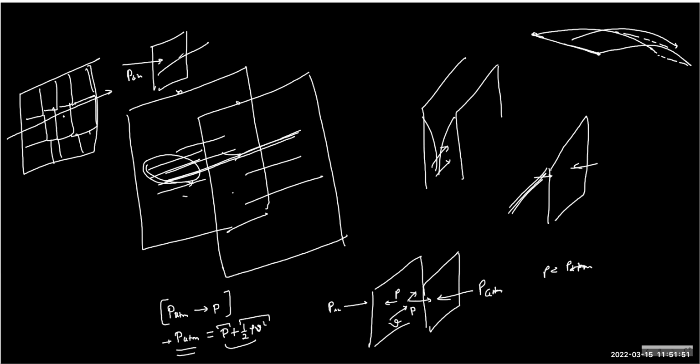So during a storm, what happens? The wind flows so fast that the pressure may drop to maybe 1/10 of the atmosphere. And this difference of pressure is really high. So how much is the force? P_atm minus P_atm by 10, into the area of the window. So they attach some frame inside which you don't see from outside.